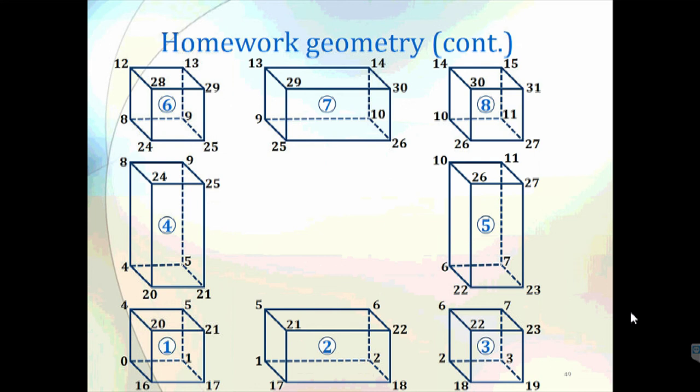Moreover, when you are specifying the boundary conditions, you have to describe a fixed wall on this side, this side, this side. Of course, it's understood, but you also have to describe a fixed wall on the inner side, on these sides. So this is also something that you should remember when defining the boundary conditions file.